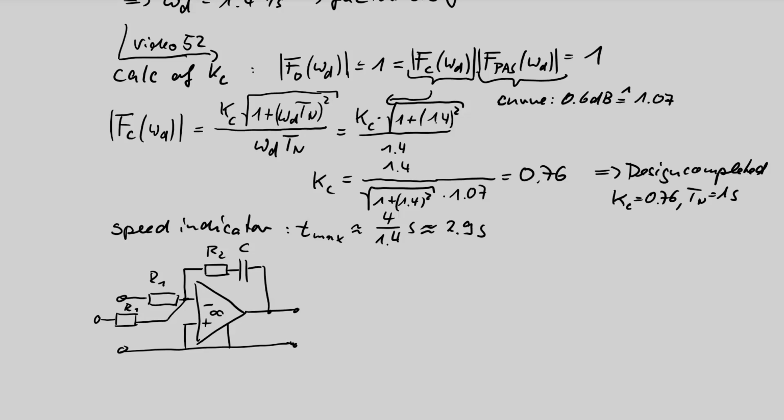Then you have an adder. The currents through R1 and R3, if this is also the same size like R1, are added at this point. So here both voltages are added, and this gives the possibility with very simple steps to calculate the control difference. If one of these signals is inverted, that makes the adder a subtractor.